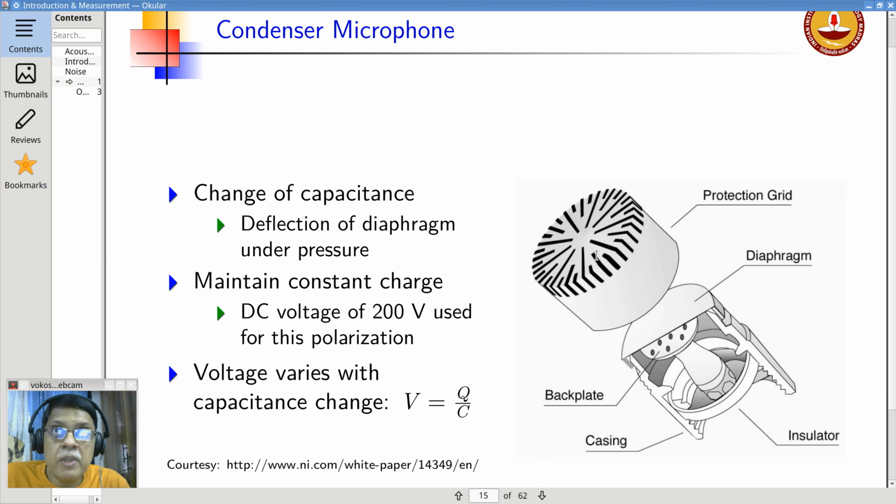Now obviously this diaphragm on the top sees the acoustic pressure fluctuations, which we talked about, 20 micropascals to 10 pascals, but it also sees the atmospheric pressure acting on it, right? This is a very thin diaphragm, it cannot take a 100 kilopascal force on it, but fortunately there is a small vent behind the diaphragm. The vent is so small that effectively behind the diaphragm I have only the atmospheric pressure. So the pressure fluctuations are filtered out because of the small vent.